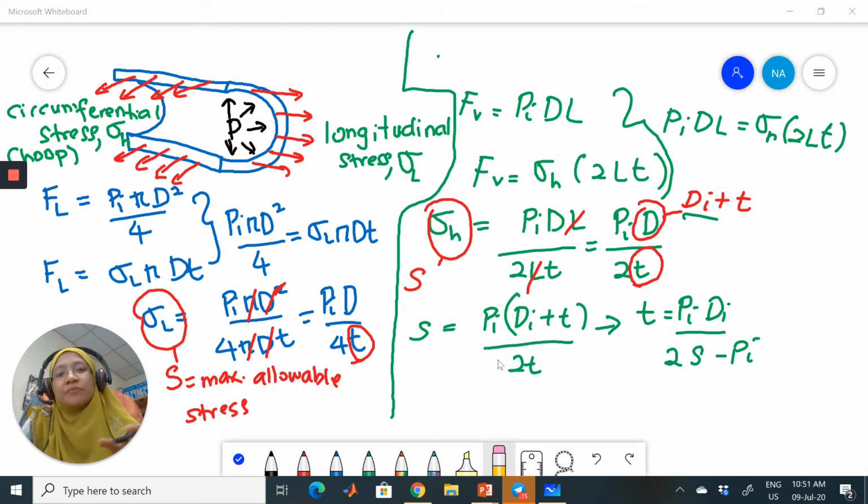Okay, so from the previous section of this video, I stopped at about to explain welded joint efficiency. So welded joint efficiency is actually used in order to show the strength. There is a possibility that when there is a welded material, the strength will not be similar to the original plate or virgin plate. But the way it is substituted inside the equation is a bit different, where it's only multiplied to the maximum allowable stress.